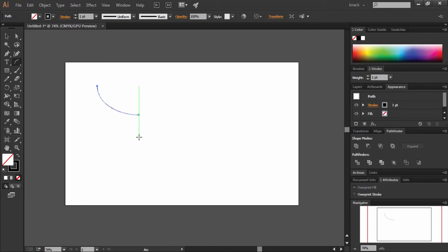Similar to the line segment tool, this tool reacts when drawn with Shift and Alt keys. Let's discuss this. Press Shift and drag to draw an arc with equal width and height. Notice the figures displaying in the measurement labels. As you drag, it will keep the height and width equal. Press the Alt key and then drag to draw the arc, making its originating point the center point. Press both Alt and Shift keys and then drag to draw a center outward arc with equal height and width.